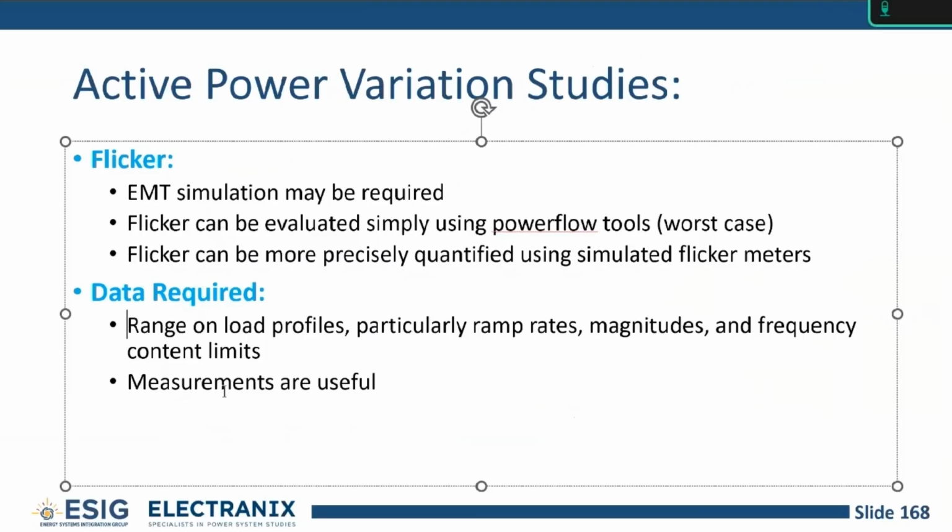So that might mean you have to lock the voltages and angles of your synchronous machines before you do your new power flow solution. And for renewable plants, grid following plants, you have to lock the P and the Q. Okay, but if you can do that in a script, then you can actually do this study in power flow, potentially. Okay, which is nice. Any study we can do in power flow, we like.